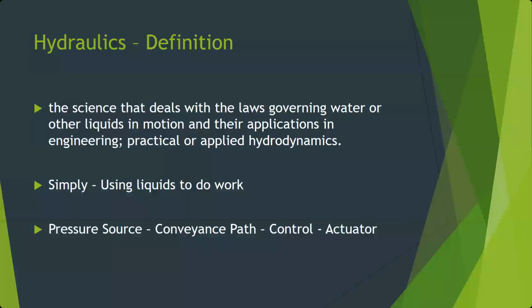We're burning it in an engine that's creating thermal and then rotational or mechanical energy. And that mechanical energy is turning a hydraulic pump to create pressure. From the electrical side, you have an electric motor driving a hydraulic pump. That electric motor's got to get its power from somewhere. And then there can even be things like the air running past the fuselage, which in an emergency we can use as an energy source to drive that pressure source.